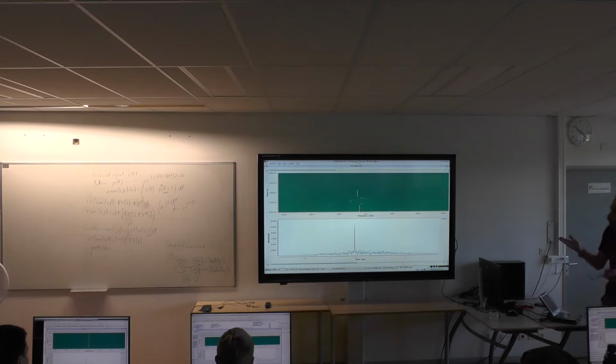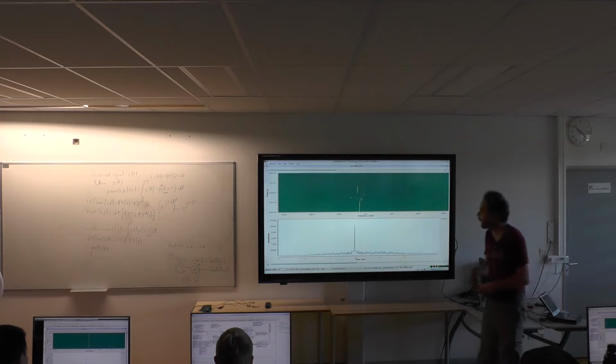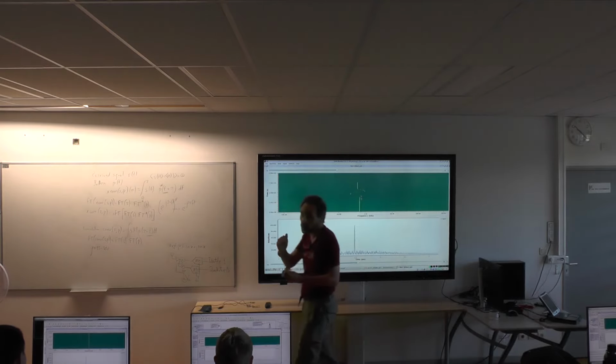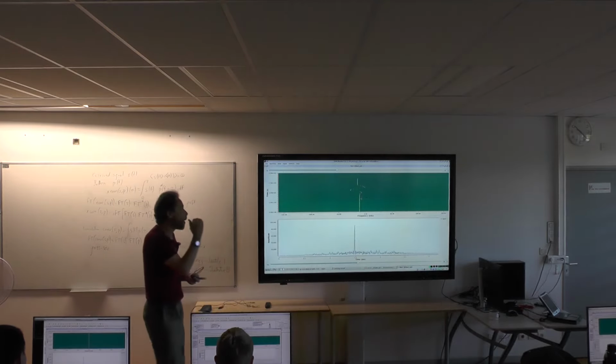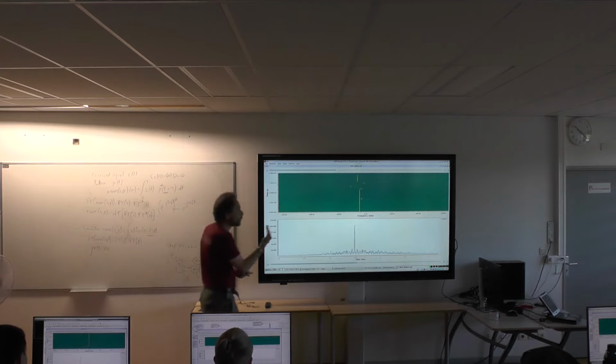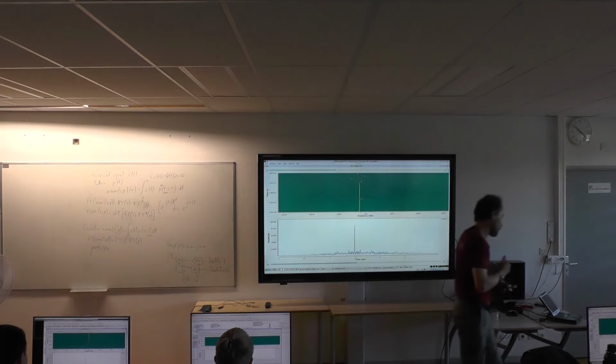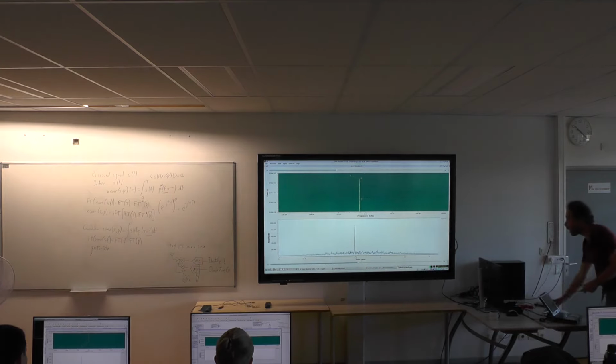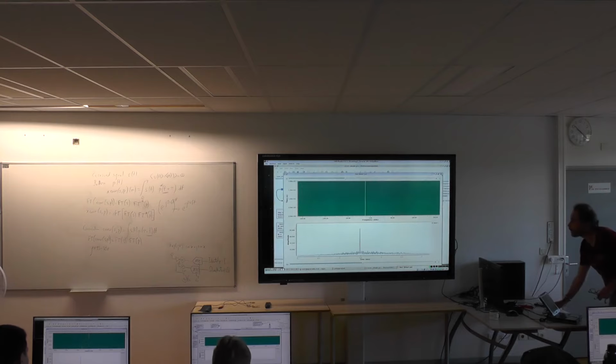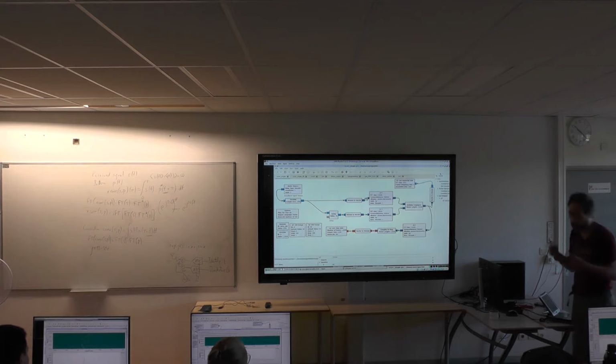So the cross-correlation, usually when we run the cross-correlation for time transfer, you don't care about the magnitude of a correlation peak. What you're interested in is the position, so the time delay, the time offset of a correlation peak. So this demonstrates how we can actually run the cross-correlation calculation in the Fourier domain.